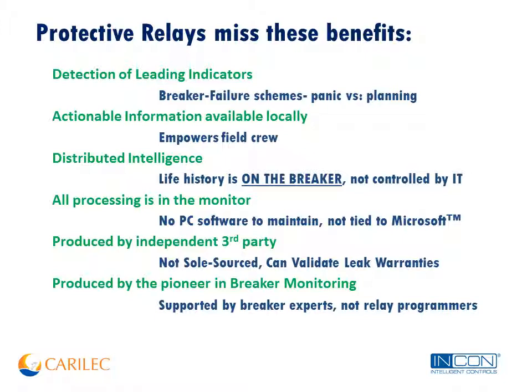Another nice aspect of the optimizer is distributed intelligence. The life history is on the breaker. It's not controlled by your IT department or your protection and control department. The breaker department, the substation equipment department owns it, and it travels with the breaker. Say you reconfigured a substation and moved a breaker. You wouldn't have to get IT involved.